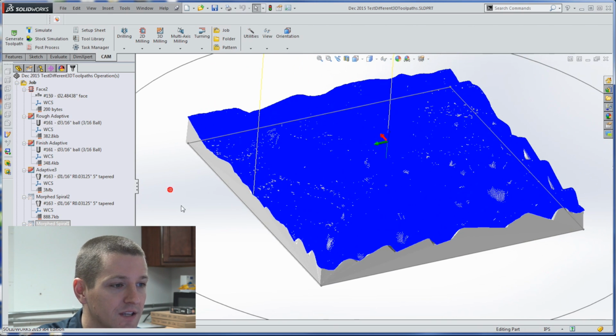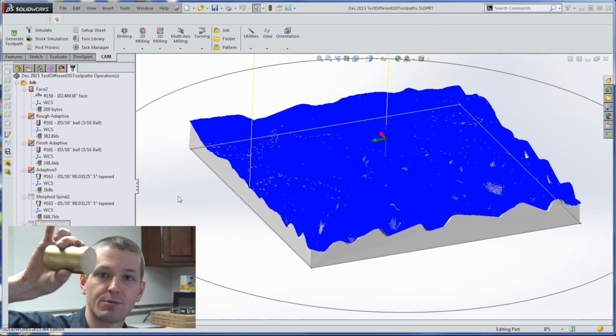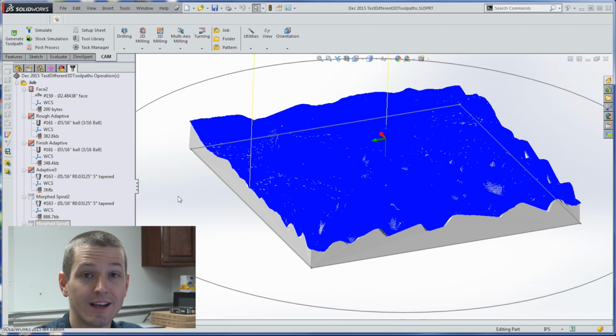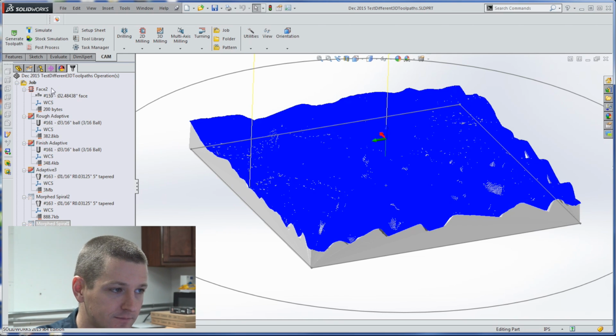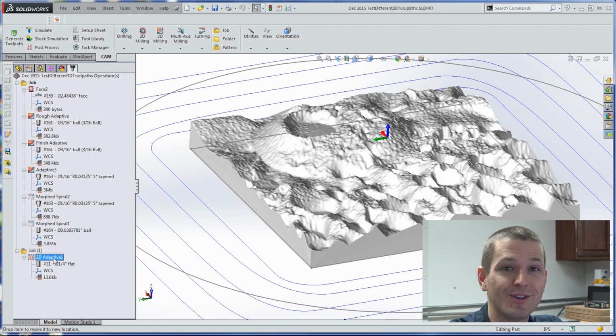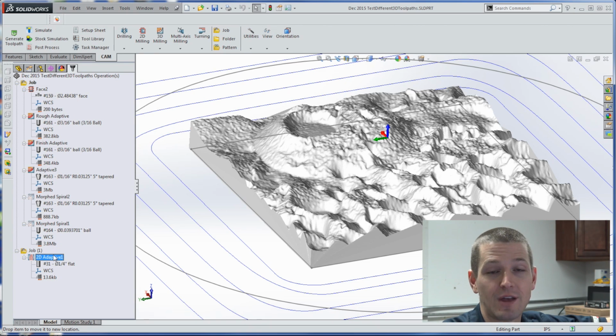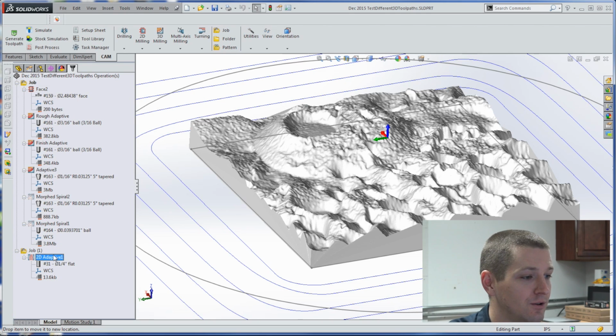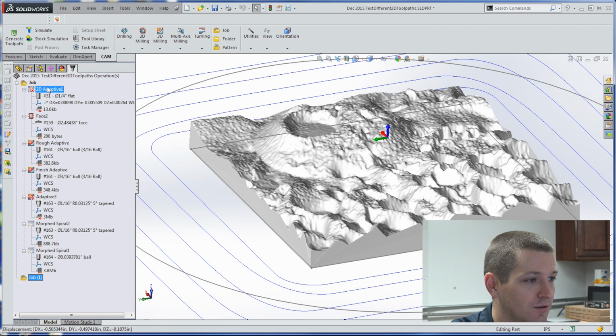So how do we make this part? We got a chunk of 360 brass free machining, should be really nice. We're definitely using the 440 because we've got the 10,000 RPM spindle. I had actually left the 2D adaptive as a separate job because I was so scared of causing my CAM toolpath to require an update, and it would take overnight to do so. But now, no big deal. I can just drag this up here and regenerate everything.